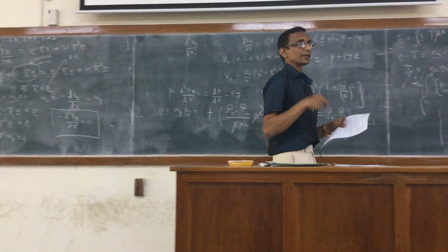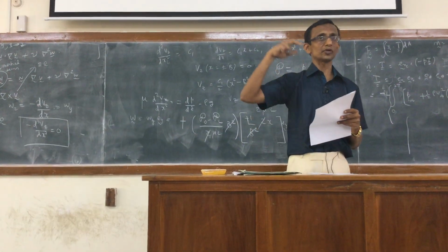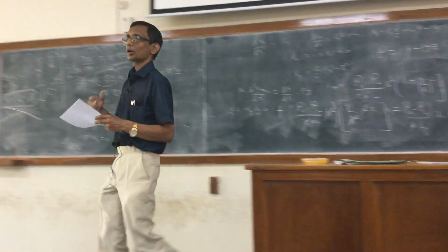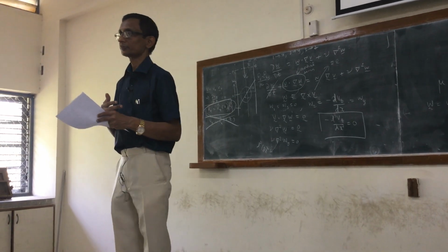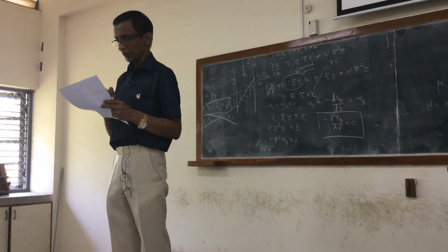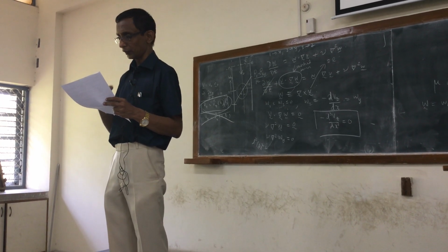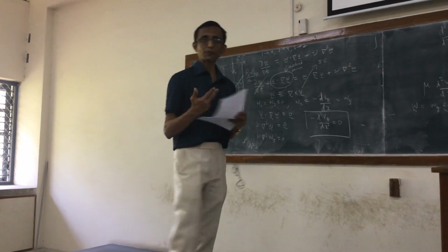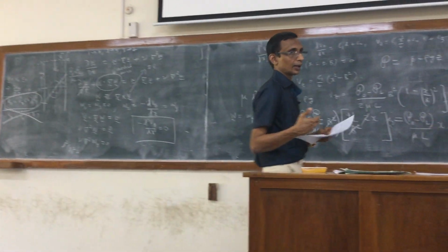One of the boundary conditions: we assume that this is a linearly viscous fluid, so we assume that both Vr and Vθ vanish on the surface of the solid sphere. Right? So that's a no-slip boundary. But here it is saying that it is a Newtonian fluid around a spherical gas bubble. So it is a gas-liquid interface rather than a solid-liquid interface.